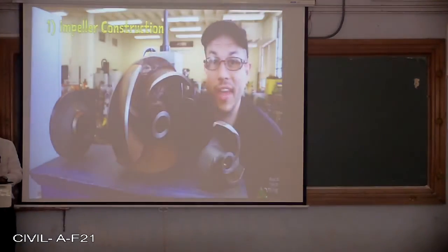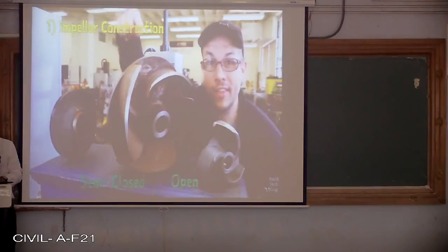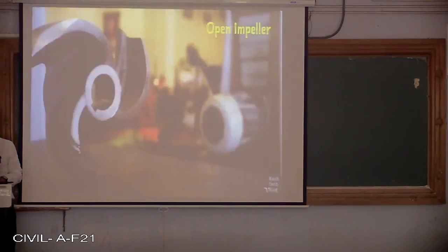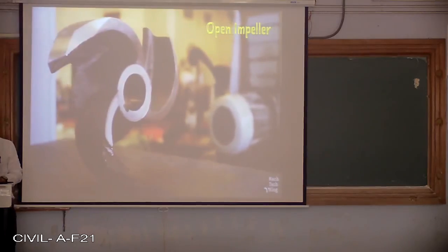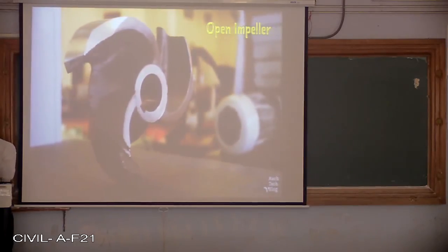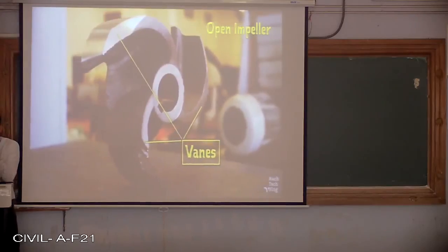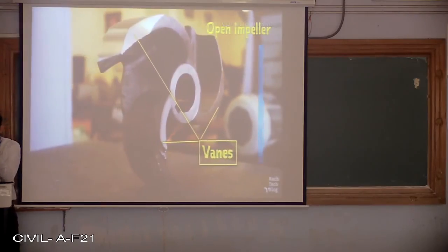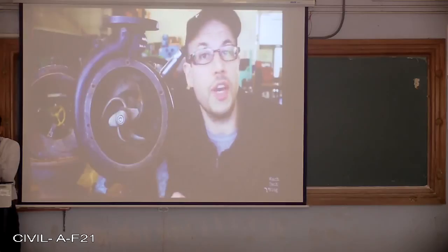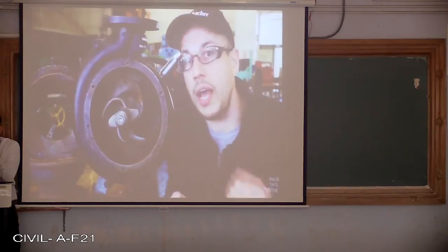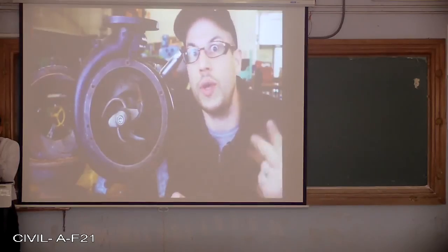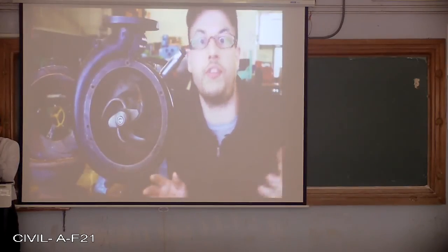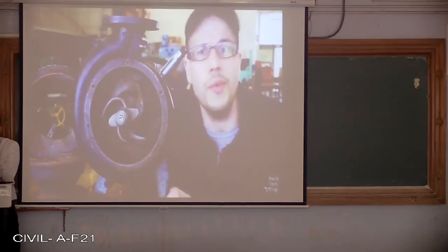There are 3 types of impeller: open, semi-closed, and closed. The simplest impeller construction is the open impeller, which consists of nothing more than a few curved blade-like vanes equally spaced around a hub on the rotating pump shaft. Large, unrestricted fluid pathways allow this type of impeller to pump fluid containing mud, leaves, twigs, sand, sludge, spray paint, cans, dead birds, you name it.